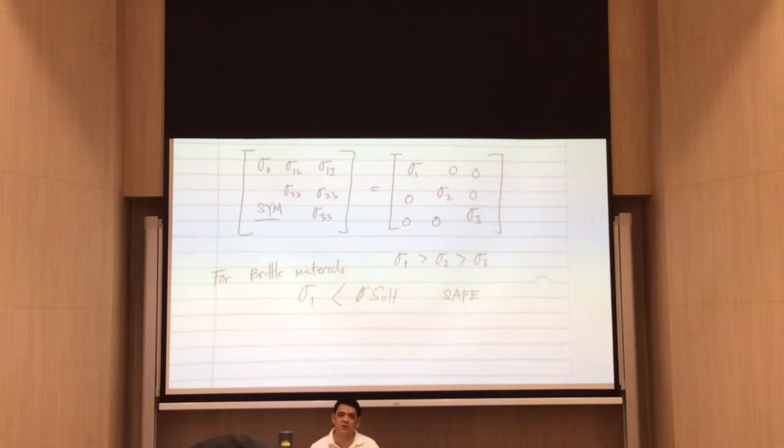Now, normally what designers do is add in a safety factor. So you have heard of that, yeah? So you have a safety factor, meaning that in order not to really go near that limit of failure, you add the safety factor. This safety factor will take into account the presence of defects in your materials, some material discontinuities, or even the environment that you have. So you have a safety factor there.